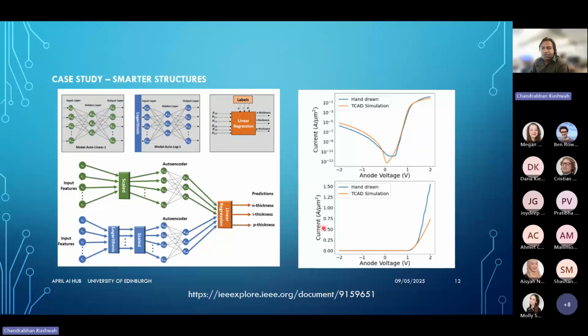To test its effectiveness, a second set of TCAD simulations was augmented with doping concentration variability to emulate the experimental uncertainties. These results show that the proposed approach significantly outperformed the conventional models, achieving greater accuracy in predicting the structure parameters, and the model proves effective for inverse design as well.